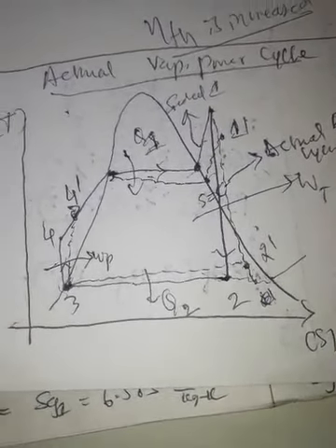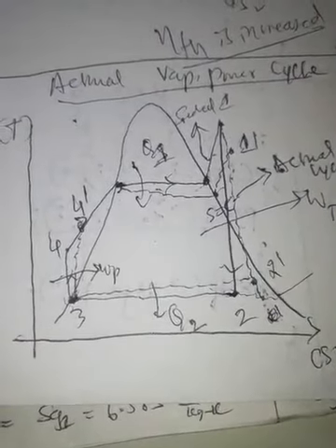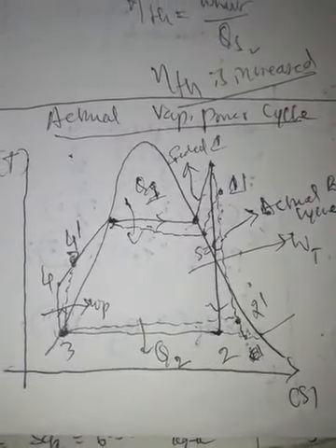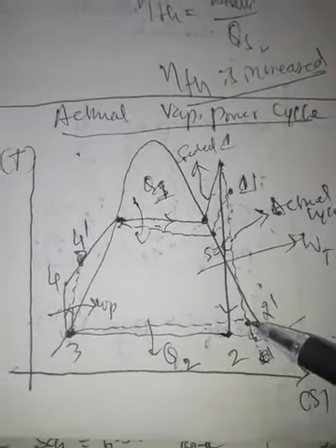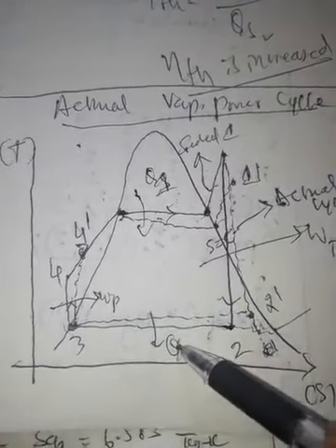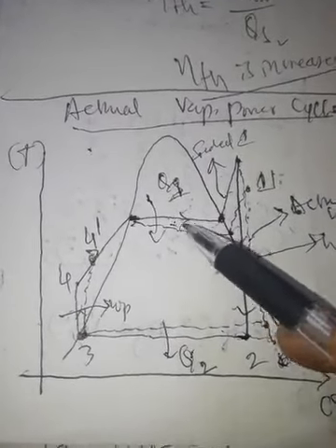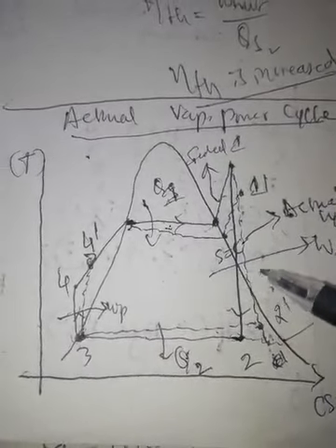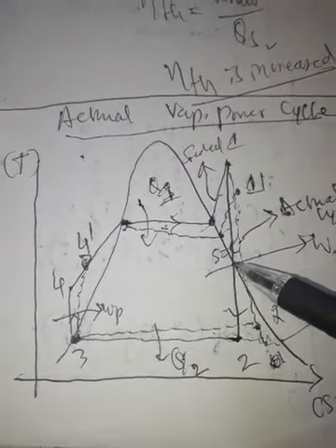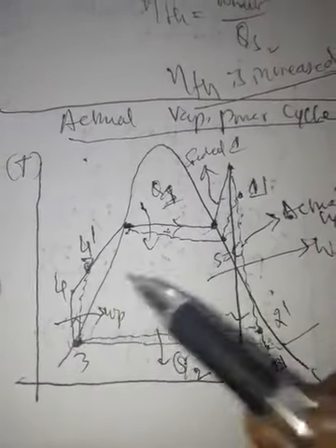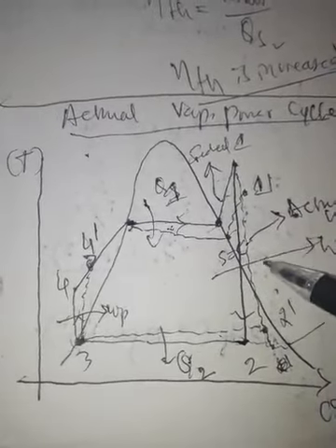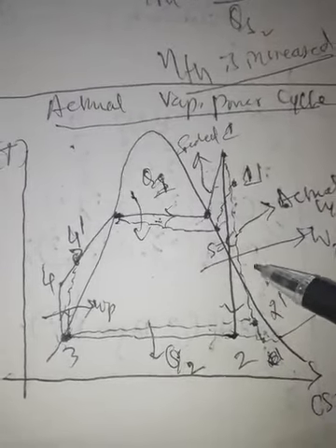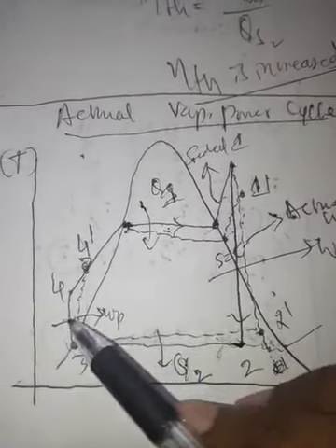So this is about the Rankine cycle. Students, for better understanding, we ignore the losses happening in the condenser as well as the boiler, and we take the losses into consideration for the turbine process as well as the pumping process, because these are machines with many rotating parts, so more losses are there. Due to that reason we consider turbine losses and pump losses.